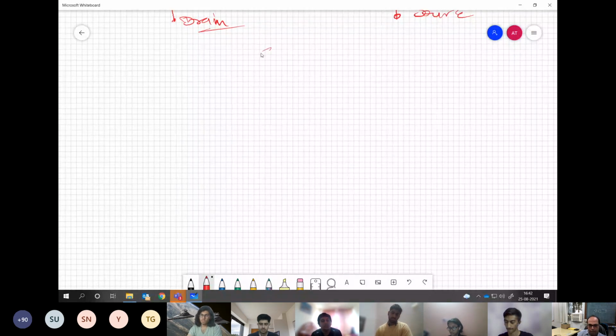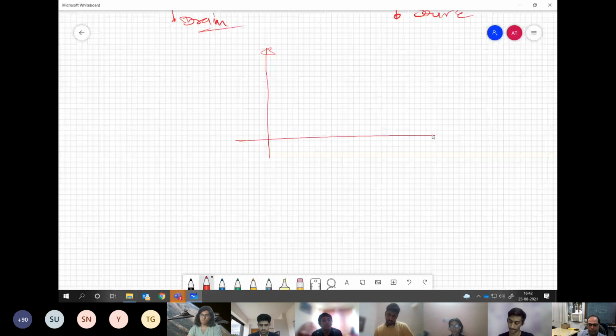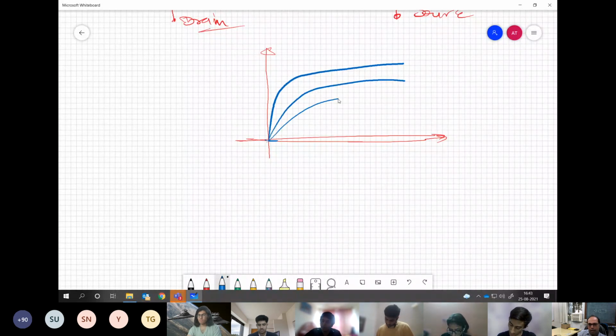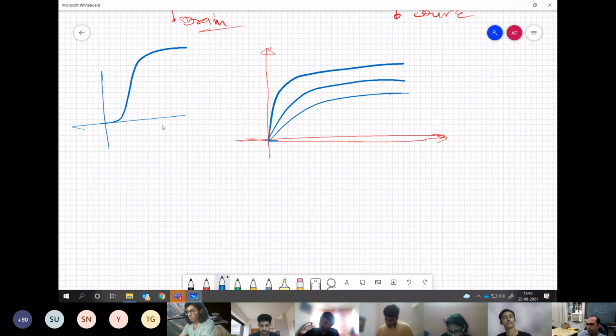So let us take the NMOS device where we are applying the positive gate voltage. The characteristic is actually very similar to BJT, except that there is no saturation voltage. The characteristic starts very close to the y-axis. There is no gap between the y-axis and the characteristic. It is almost as if it is starting from zero. The BJT had a small gap and then it starts. So notice this difference. Here, this is what is responsible for VCE SAT. Here, there is no such thing. Understanding my point?